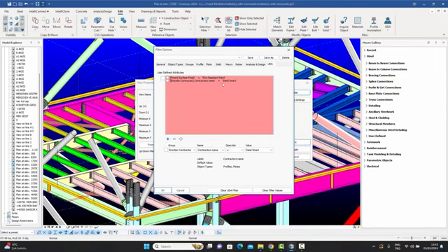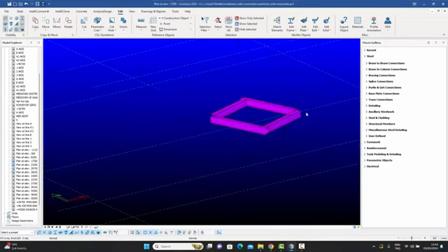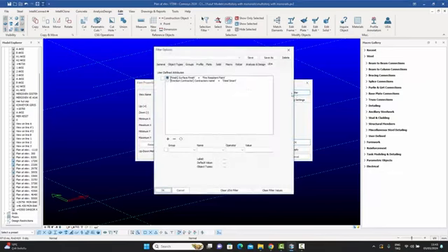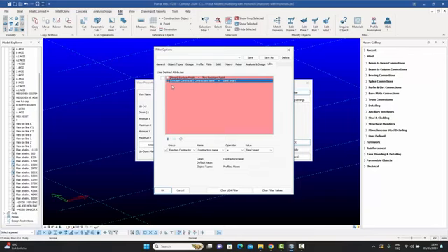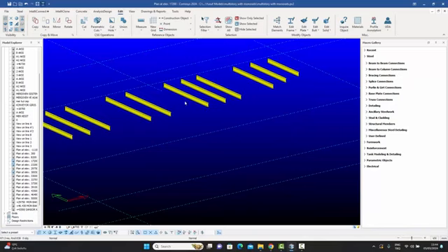Now I've got two filters up there, but I don't want to use both of them. I just want to see, if I select this one, this means I want to see which ones have the fire resisting paint. So if I don't select them, this one is not in play. Only the one which is selected is in play. When I do that and I press OK and OK, immediately only the beams which have fire resistant paint are left on the screen. Similarly, if I were to go back and change this from this to this, now I have the other one in play. And now I see that these are the beams which are going to be erected by the contractor called Steel Smart. So this is a very handy way and the most obvious way of using the user-defined attributes.